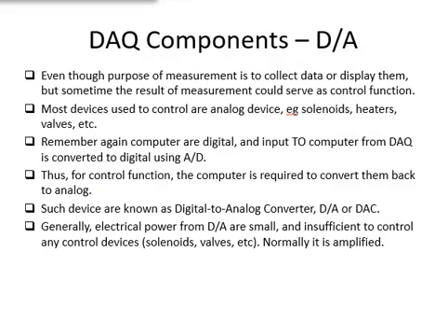While in some situations a data acquisition system is used only to collect data, it is common for the computer to use the acquired result to change some aspect of the measurement system. In a process plant, this will be a control function. In an experiment, it may be a control or it may be a variation of some independent variable of the experimental apparatus.